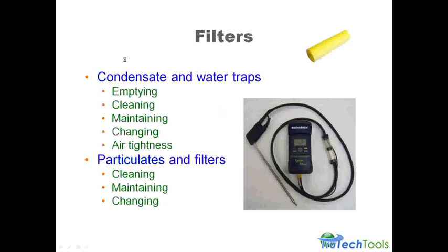The filters on most of them get dirty from the inside out. So if the filter looks clean on the outside, it's still good to use. If you're using them on natural gas, you may need one filter a year, or maybe even one filter every 2 years, because there's just not any dirt in the flue gas to contaminate the filter.